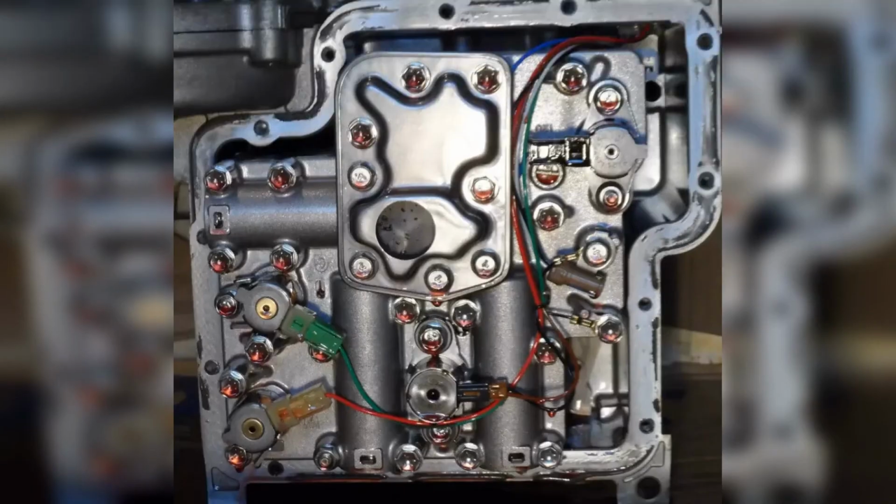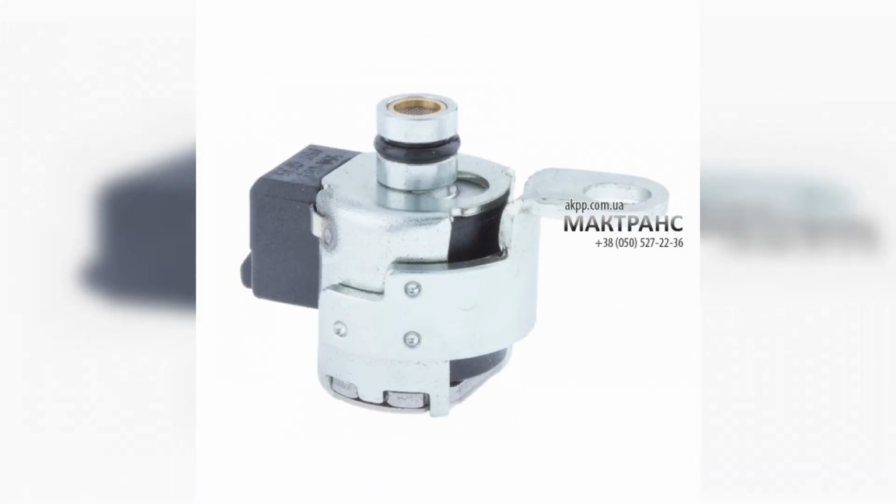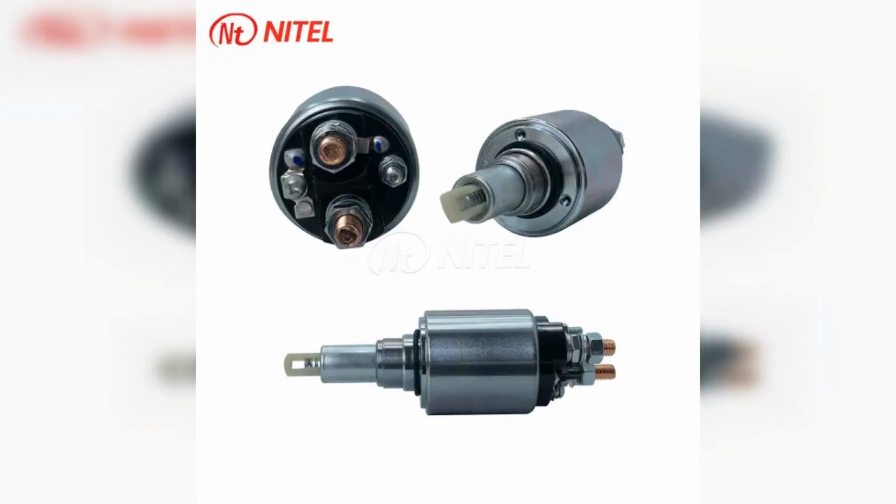Depending on the symptoms, the P076C error can be moderate or severe. If there are problems shifting gears, it is advisable to rectify the fault as soon as possible. Causes of the error. The P076C code may mean that one or more of the following problems have occurred. The H-shift solenoid valve is faulty. Contaminated fluid or clogged gearbox filter.